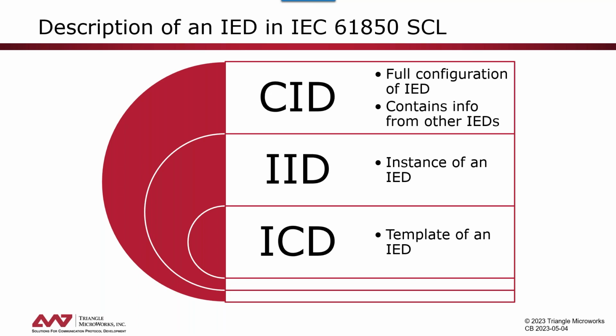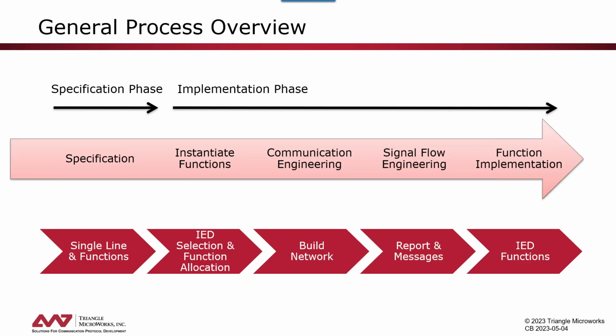They can describe a template of an IED, the ICD file, or an instance of an IED. In the case of an instance, the file contains already some specific configuration information for the system in which it will be deployed, like IED name or communication parameters. The engineering process with IEC 61850 will be the focus of today's webinar. We will start to introduce the process as it is supported today. At the end of the webinar, we will provide a little preview on some future developments regarding this engineering process.